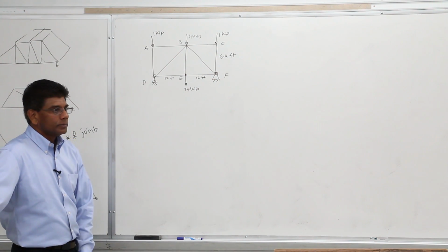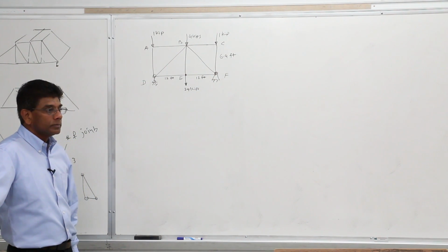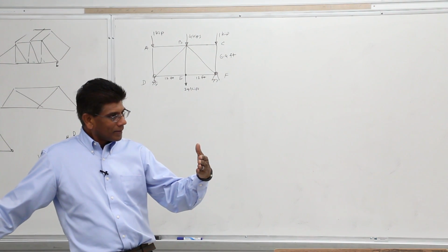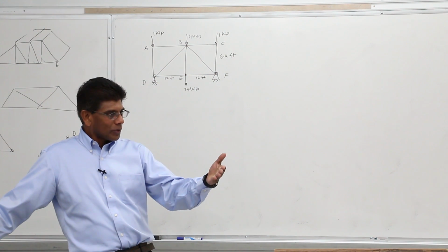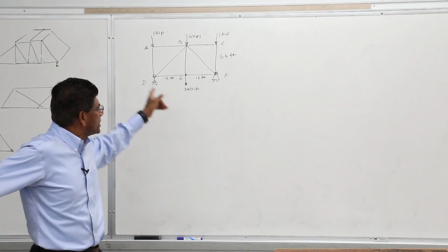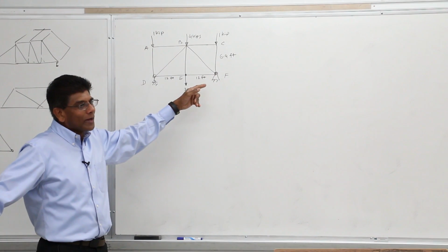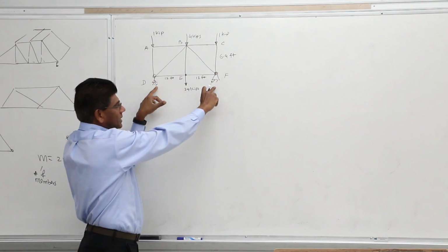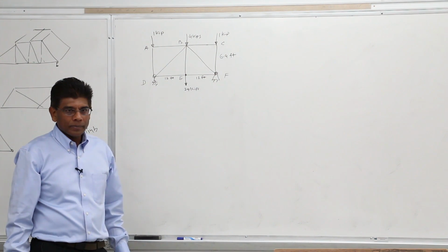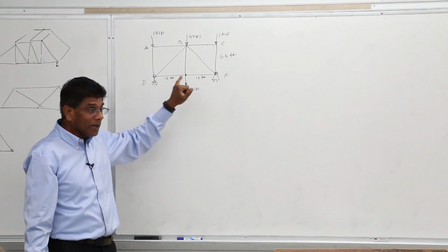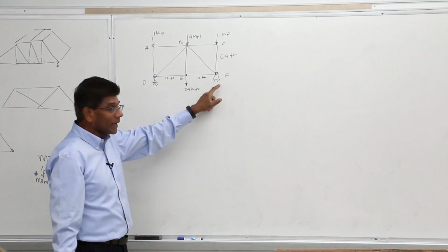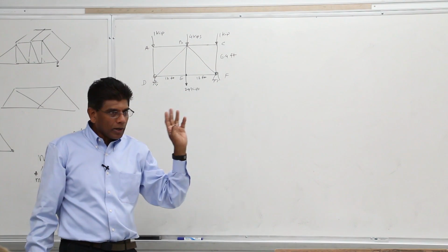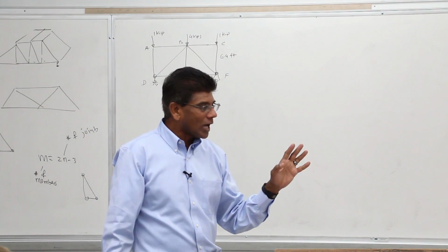Make it a box and try to solve that. I want you to reframe it. Say that again properly so everybody can understand. What he is saying is, consider this instead of a box. I would like to use a better technical term. Use the complete structure, but disconnected from the supports. That means we'll have 3 unknowns, and it is a 2D rigid body equilibrium problem. 3 unknowns. You know there are 3 equations, so you can solve for them.